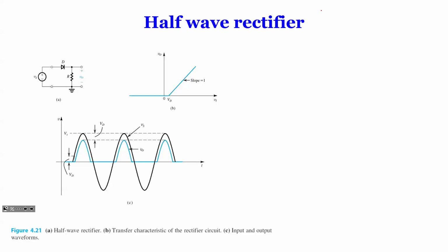All right, so this is the simplest diode circuit that you can get, connecting an AC source through a diode to a resistance. We have illustrated how it works many times. If it's a real diode, you would have a little bit of voltage drop. Therefore, the output, the blue line, is a little bit less than the black line.